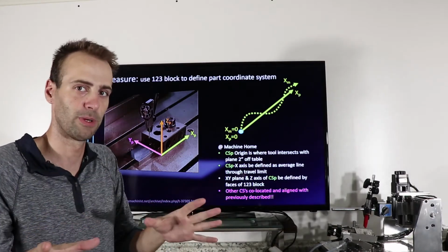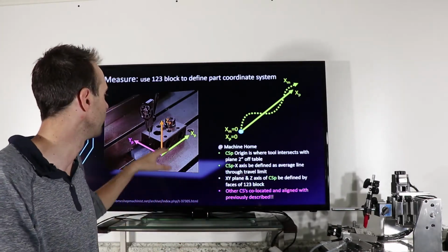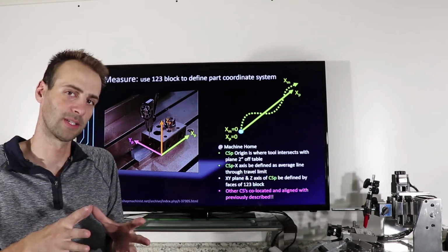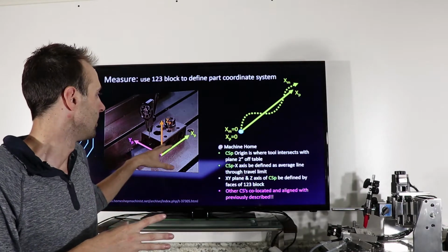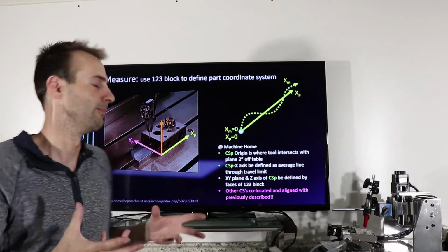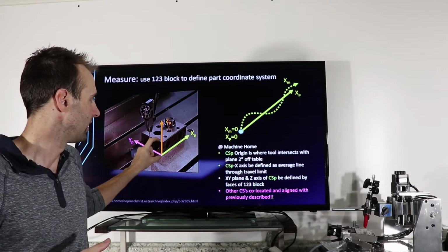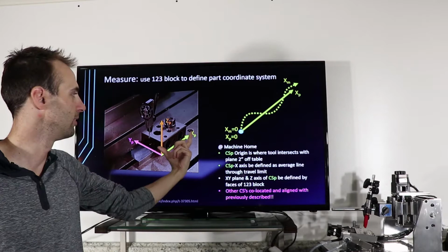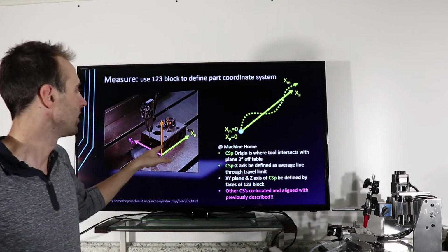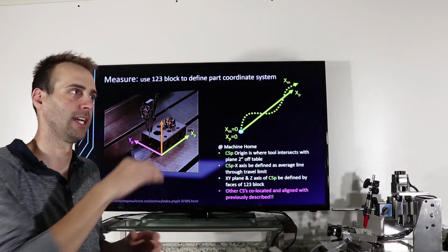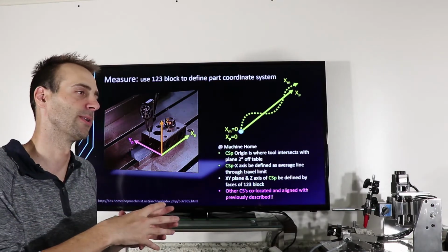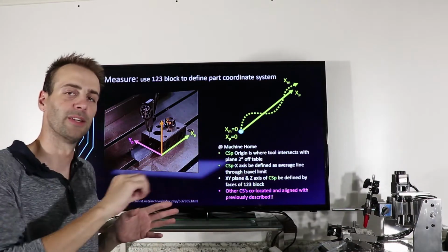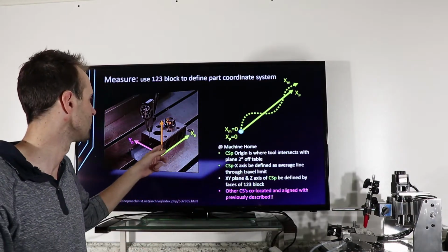But don't just put it anywhere. Think about where you're putting it, and you want it to be in the same spot as where your parts are going to be made, and in the orientation that makes sense for the machine. So for example, the height of this is only 1 inch, right? If this is a 1, 2, 3 block, my width is 2 and my length is 3. So my critical axis is going to be X, because that's what I tram my vise to normally. That's where my longer cuts are. I want as much measurement length on my x-axis as possible, okay?